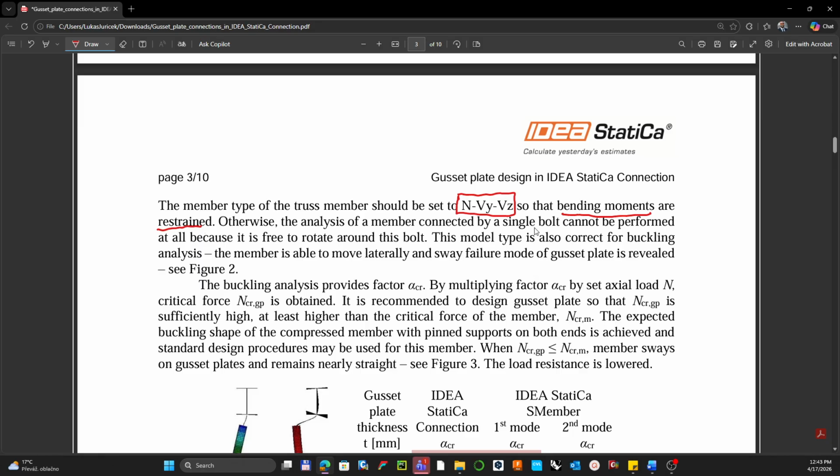As I mentioned before, or I'm not sure if I mentioned, if you want to know what happens once you turn those constraints on, all the rotations, Rx, Ry, and Rz, are prescribed as 0. It means there is no rotation allowed at the end of the condensed element.